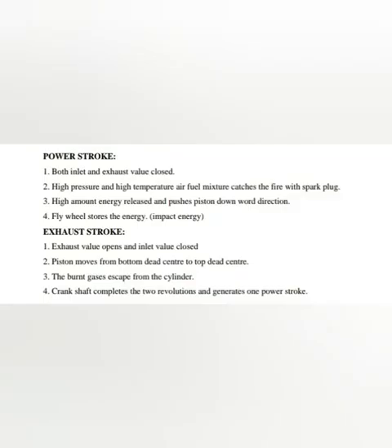Third stroke, power stroke. This stroke is also called the expansion stroke or working stroke. During this stroke, both the valves remain closed. As the combustion of the fuel takes place, the burnt gases expand and exert a large force on the piston, causing it to move rapidly from the TDC to BDC.